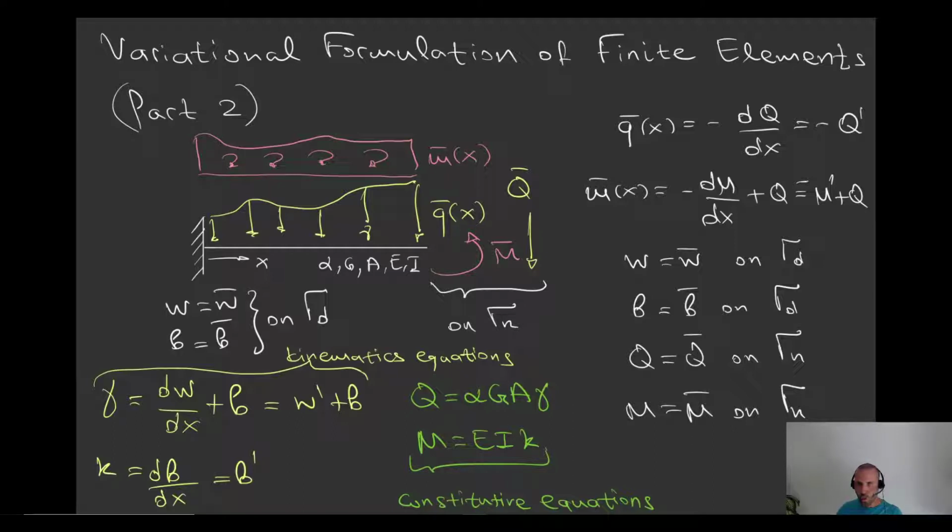All right, what we've seen so far in the first chapter, where we talked about the Timoshenko beam formulation and its finite element discretization, we saw that we applied those subsidiary conditions, like the kinematics equations and the constitutive equations, strongly into the problem. How can we tell that was a strong imposition? Because we actually used the variational formulation at the time. We called it the principle of virtual work, and we simply went and substituted these equations directly into the weak form. By doing so, we impose these conditions strongly, which means that the solution doesn't have the flexibility not to fulfill these equations.